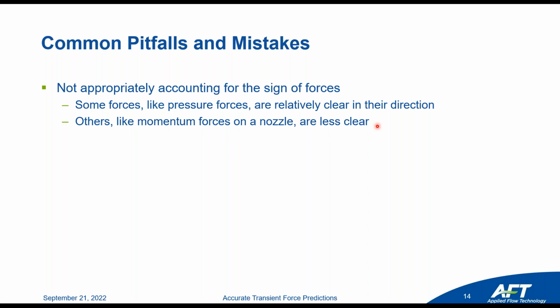So the force on the nozzle must be towards the fireman. But that's really not the case. If you cut the nozzle off of the pipe, it's going to go forward, not backwards. So if you don't add up all of those signs correctly, you're going to get some kind of incorrect result, depending on which signs you got wrong. So you have to be very careful about that.